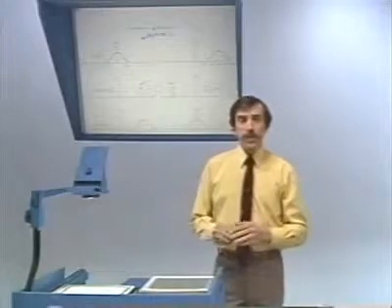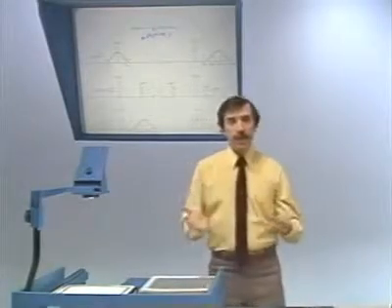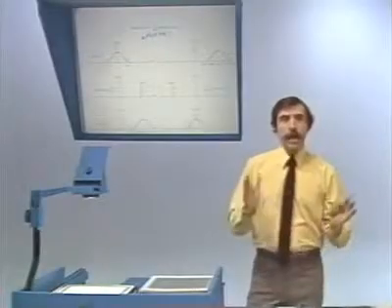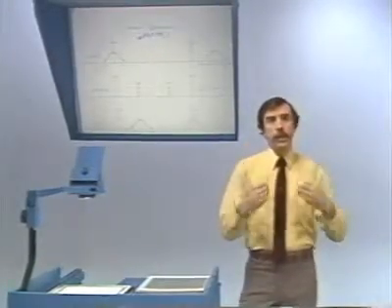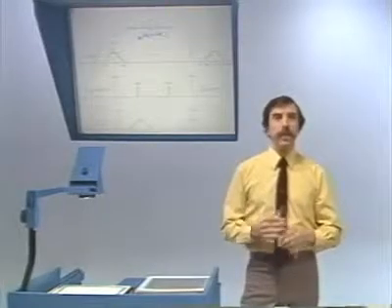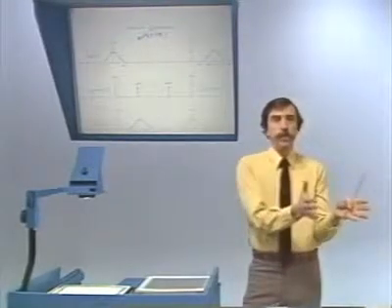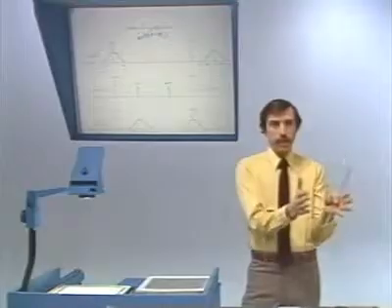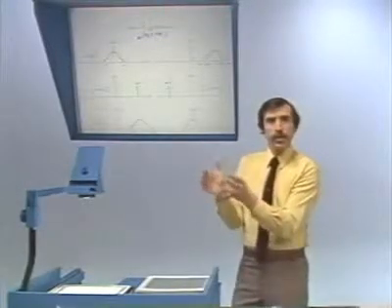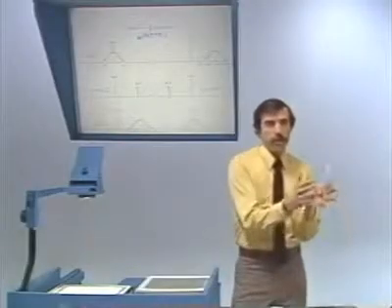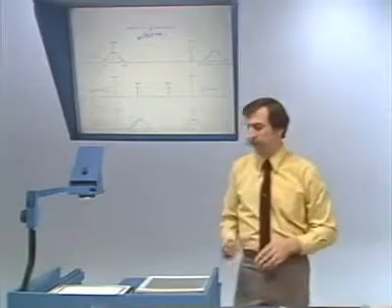So what this says is that if we have a signal, x of t, and we use it to modulate a complex exponential carrier, in the frequency domain, what we've simply done is to take the original spectrum and shift it in frequency so that what was originally at 0 frequency is now centered around the carrier frequency.